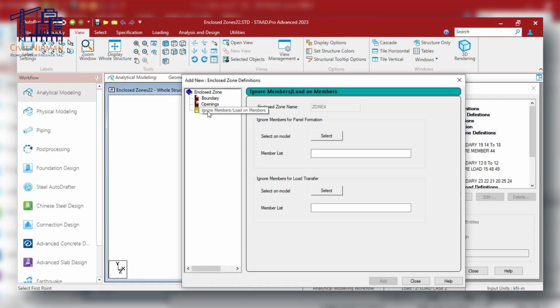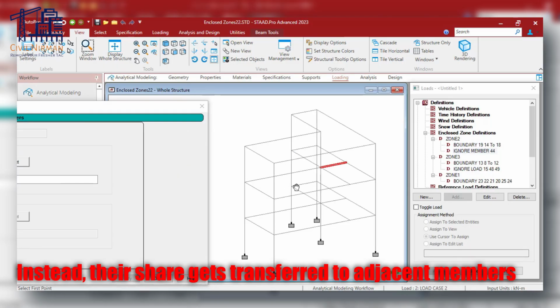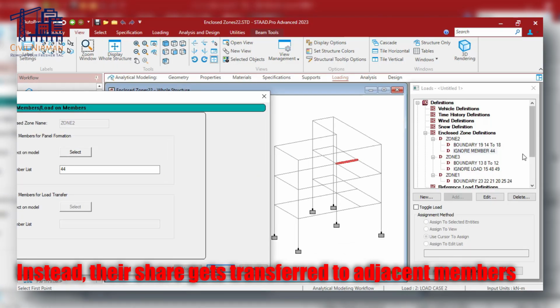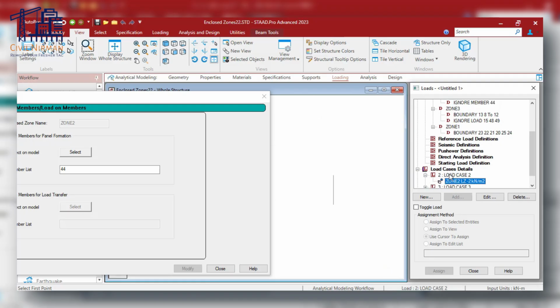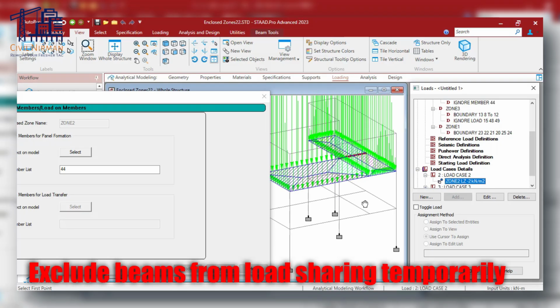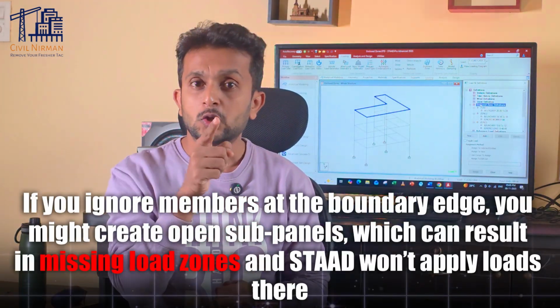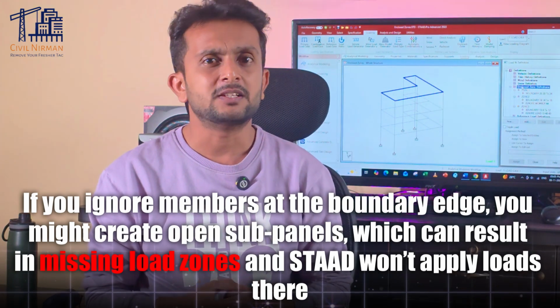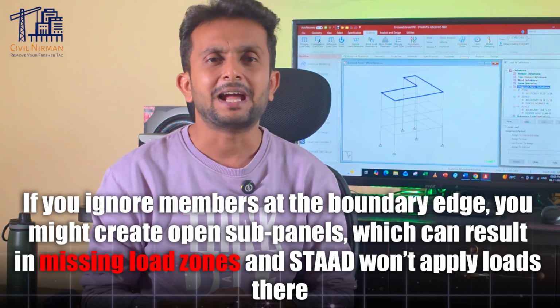You can also specify certain members as ignored for load transfer. These members wouldn't receive any load. Instead, their share gets transferred to the adjacent members. This is super useful when you want to simulate one-way slab behavior or exclude beams from the load sharing temporarily. But be careful. If you ignore members at the boundary edges, you might create open subpanels, which can result in missing load zones, and STAAD wouldn't apply loads there.